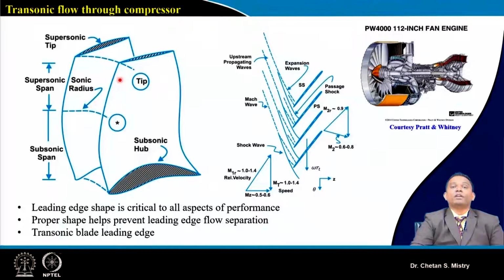We know from our fundamentals of gas dynamics that when we have supersonic flow, we are looking for a sharp edge. So here, this represents things in the sense of my Mach number. As we have discussed, suppose we are considering our fan facing the flow, we are looking for an entry Mach number in the range of 0.4 to 0.5. So this is in that range, and my relative Mach number is coming to be large. Okay, so this represents my flow being a supersonic flow that is entering inside my flow passage.